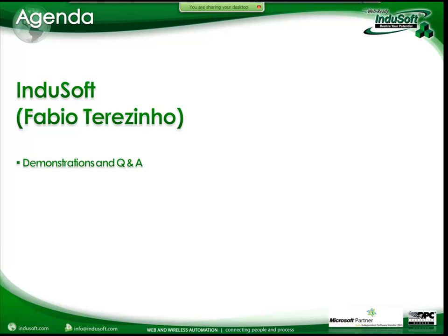One of the advantages in the Software Studio is the fact that you can create tags from anywhere, even when you are creating screens, and then create worksheets to talk to the PLCs, go back and create more tags, more screens, so you can evolve your project naturally. But again, the most important thing is to plan ahead, so everything that you create in the application is consistent and flexible enough to evolve as the project continues.